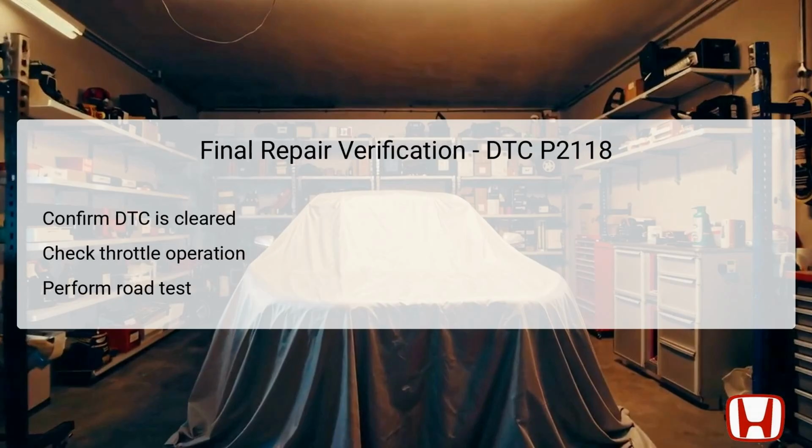After completing the necessary repairs for DTC P2118, it's crucial to verify that the problem has been effectively resolved. Start by confirming that the DTC has been cleared from the system using the HDS. Once the code is clear, test the throttle actuator's operation by pressing the accelerator pedal to ensure smooth and responsive power delivery. Finally, conduct a road test to evaluate the overall performance of the vehicle under normal operating conditions. Ensure that both engine performance and throttle response line up with expected standards. Ensuring these steps are carefully followed will help confirm the integrity of any repairs made and guarantee that the issue has been fully resolved.